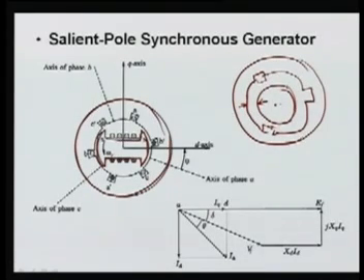Here the pole is a field winding, where we can have a formation of N and S, which can be obtained by having the winding on the rotor. So you can say this air gap is uniform, so the reactance between the stator and the rotor is constant. But in the salient pole machine, the air gap is larger up to this value, and here it is very small.